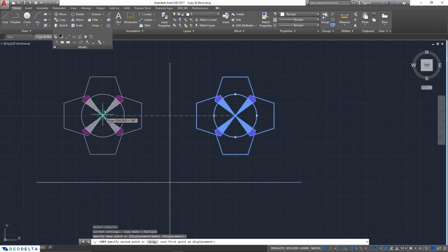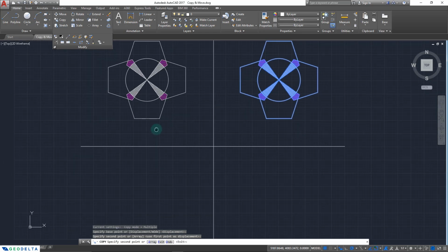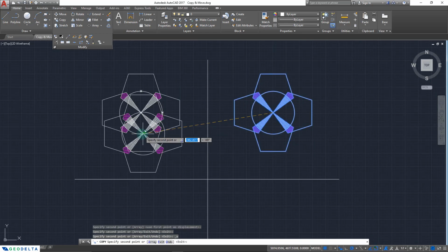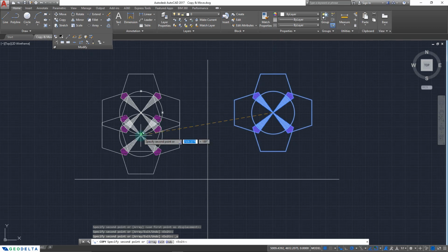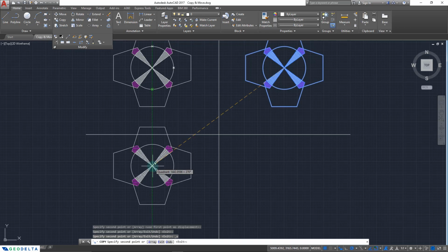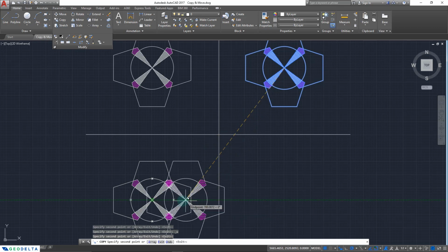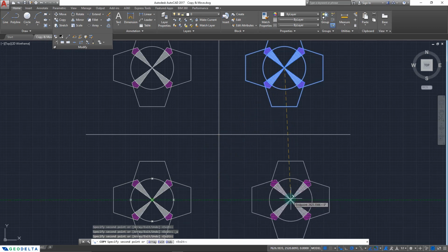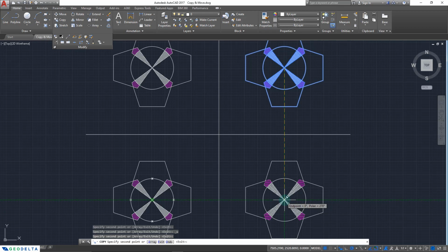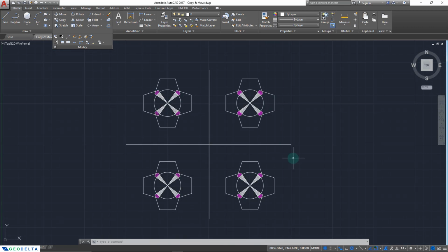And I'm going to place it somewhere over here. And even if I place my first object, now you can see that we are not done yet. We can simply go ahead and make another copy in this quadrant as well. And I'm going to tap once on this lowest point of the circle of the second object, just so that I can activate the polar tracking, so that I can move my third object along this line. Another copy right over here. And similarly, I'm going to make my final copy in this final quadrant at this particular location as well. And once you're done with everything, you can simply hit enter. And finally, this is how it looks. So that's about it for copying and moving objects.